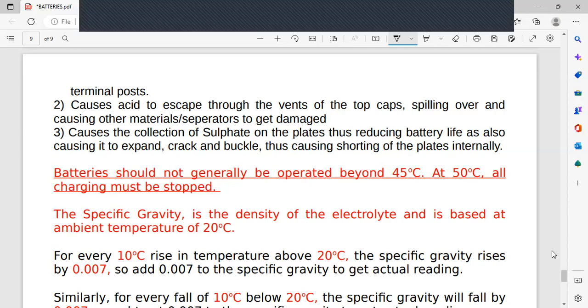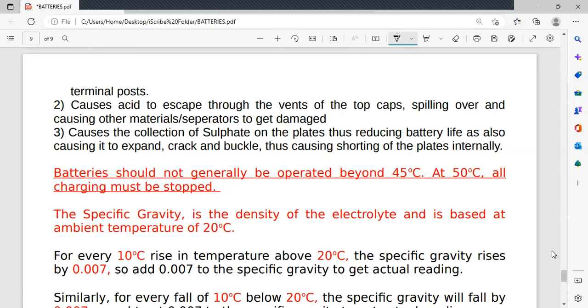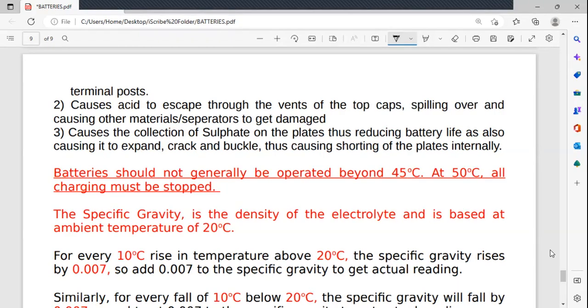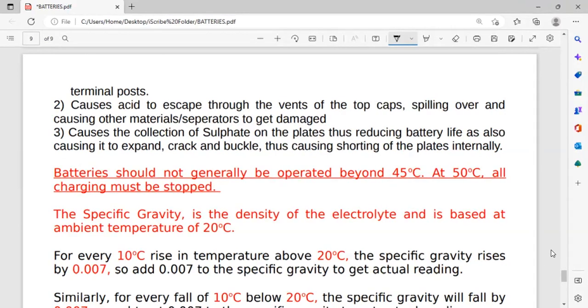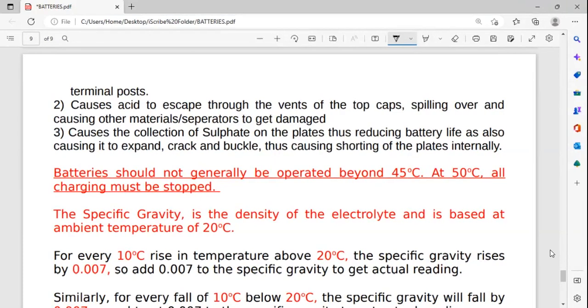Okay, so what had happened? I had disconnected the battery charger for the emergency generator batteries, and I had come up to the bridge to disconnect the batteries from your battery charge discharge panel. And when I got this call, I forgot about that, went down, and by the time the inspection, etc., was over, I came up and found that at least 2 of those batteries had exploded. Okay, so this is what had caused that.